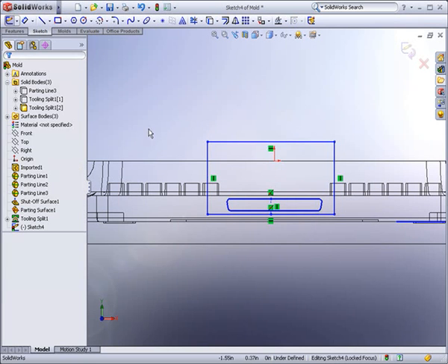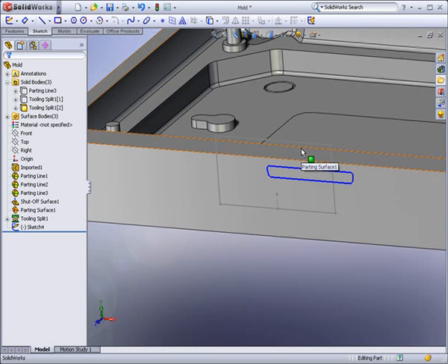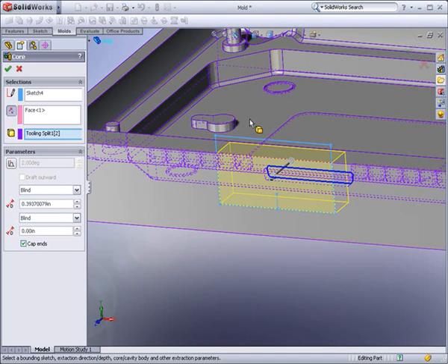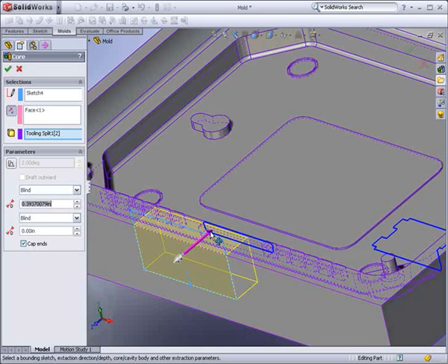Using the side core tool, simply drag and drop. The preview in the graphics area provides feedback that specifies exactly what size you need to make the side core. Now, we have quickly created the 3 pieces of core geometry required to generate the injection tooling.